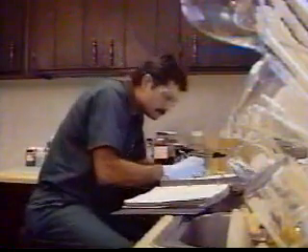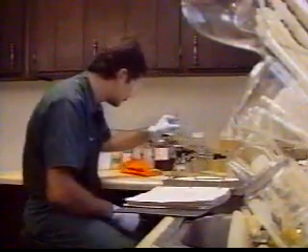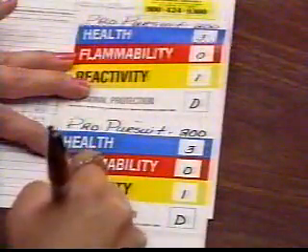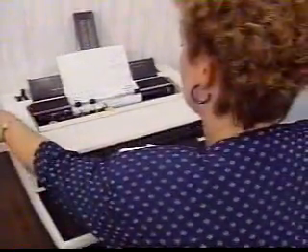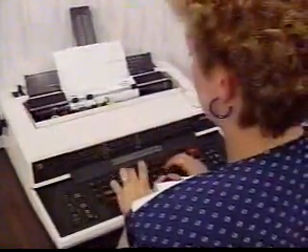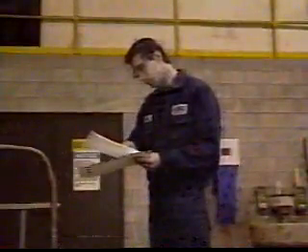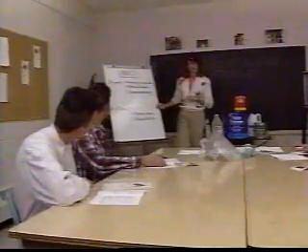The standard first requires the chemical manufacturer or importer to evaluate each chemical for hazardous properties. The manufacturer then places the evaluation results on container labels and on a form called a Material Safety Data Sheet, or MSDS, which comes with the initial chemical shipment. Your employer should then review each MSDS and label and pass that information along to you in a training session.